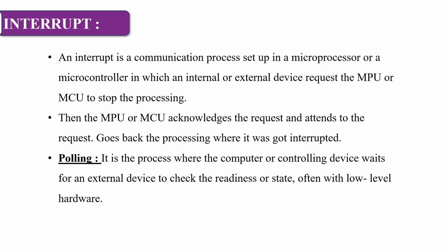It is simple: when we are running a program, the interrupt interrupts the code to execute another part of the code, and after executing that part, it returns to the previous code and continues from there. The MCU acknowledges the request, attends to it, and goes back to the processing where it was interrupted, after the ISR function executes.